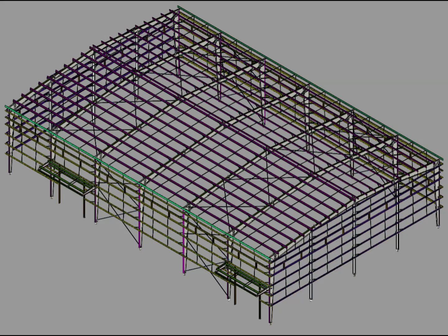So, the main point to remember from this first slide is very simple. A sag rod is a secondary rod member associated with the purlin framing system, provided as specified by the structural design to help restrain and maintain the secondary members. It is not the same as a roof purlin, and it should also not be confused with rod bracing. We will understand those differences in detail as we move through the next slides.